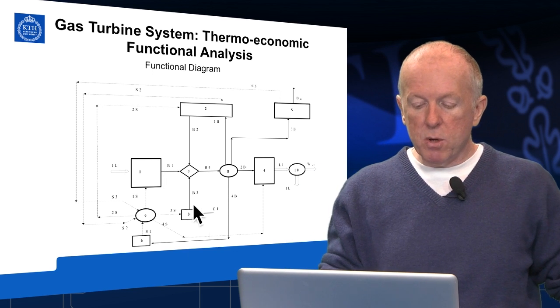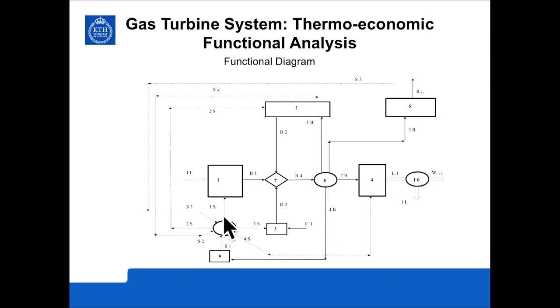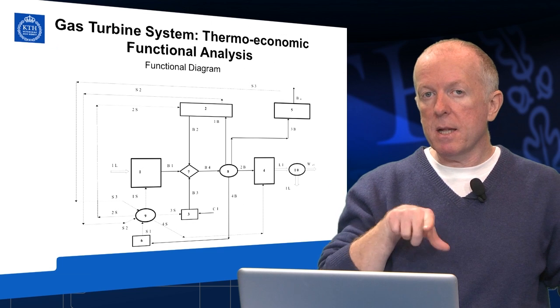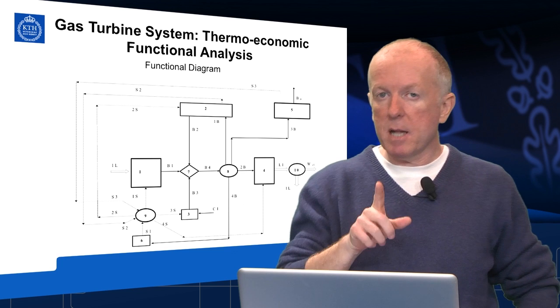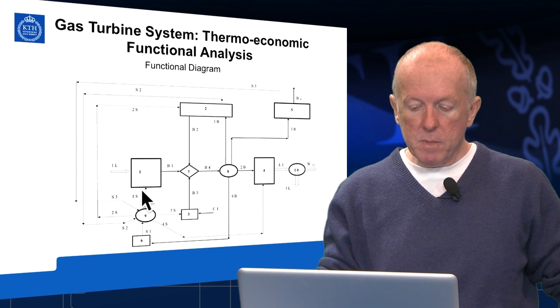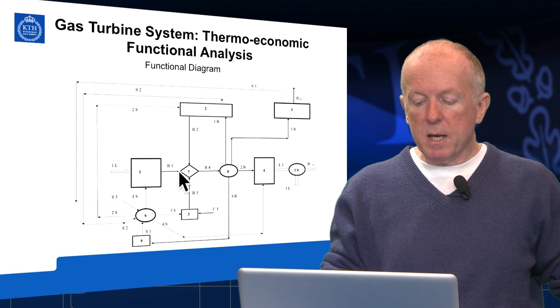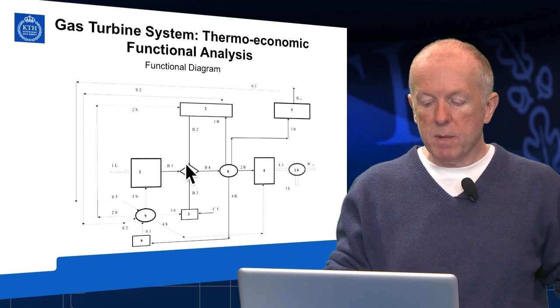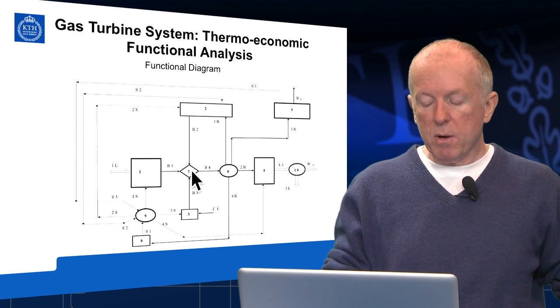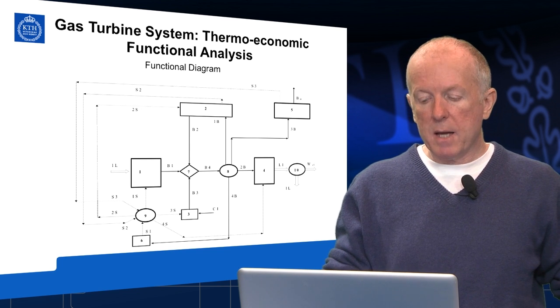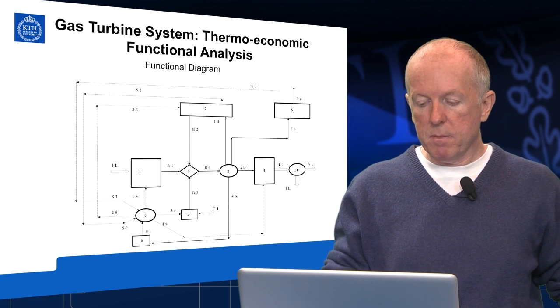But please notice that the compressor has another resource, the resource 1S, which is the negentropy flow given to the compressor because it produces entropy. So it has to be compensated in terms of inlet negentropy. This flow B1 is given to a junction 7. The junction receives an exergy flow from other components.